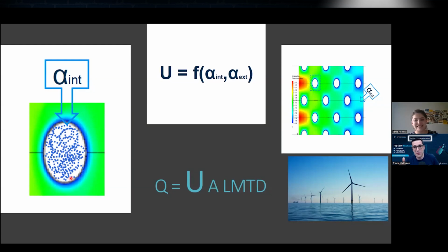But I've noticed over the years of diving more into heat transfer, I look at the pressures and I see the temperatures, and I can actually understand what's happening inside that pipe. And that's where we know that this coil is full of liquid, or it's full of gas, or it's starting to condense at this point, just through temperatures and pressures in the system.